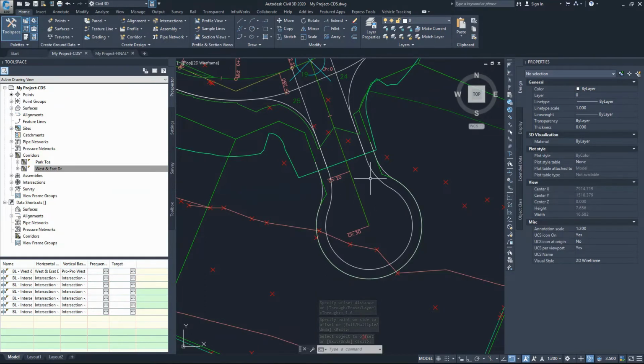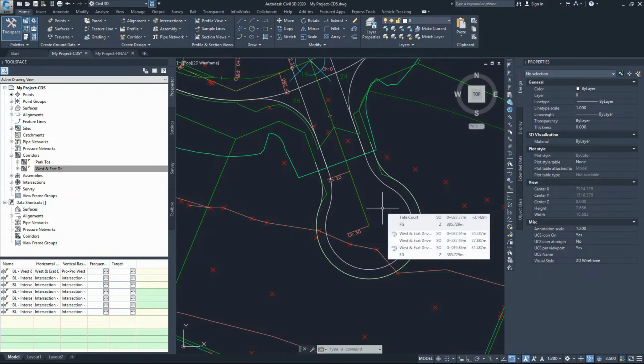All we did so far, we just created the outer line, we offset that by 1.6 to create a polyline continuing the curve returns. We are trying to create another one of those alignments, continuing all the way inside the Cul De Sac, turning around and coming to the other end. It's always easier to work with polylines to start with, kind of sketch your design, and then start refining your design to an alignment and profile and the rest of it.